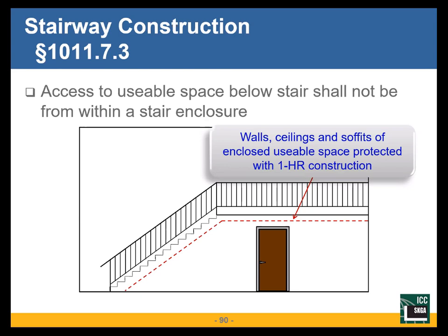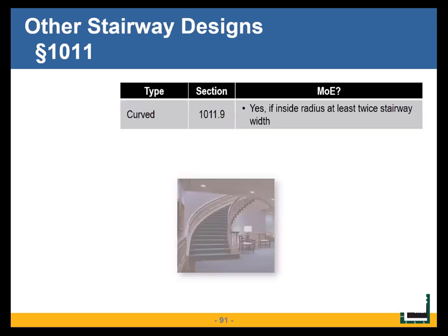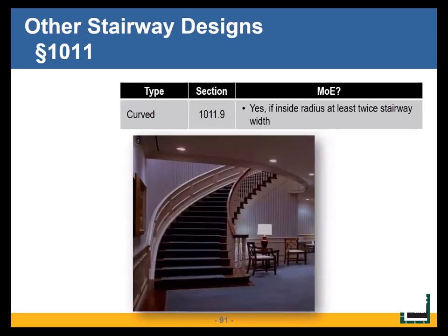If I'm in a stair enclosure, my interior exit stairway, the answer is no, you cannot. So this would be applicable to an exit access stair. Can I store beneath that? Yes, you can, as long as you separate it with 1 hour construction. So what type of stairs do we have that are allowed as an egress path?